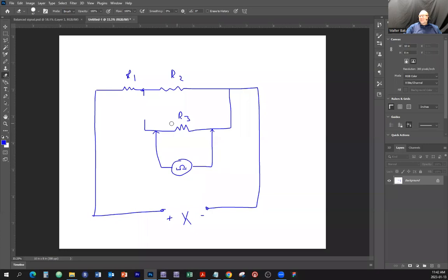Now, so that's considered as lifting one leg. Now, careful with this statement here. I said often one leg is enough. If you have just a freestanding device, a battery operated meter, lifting one leg is fine.